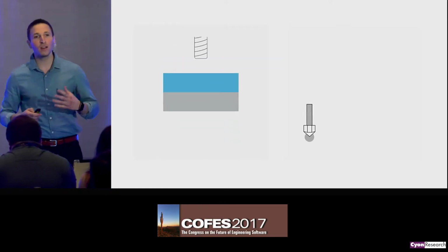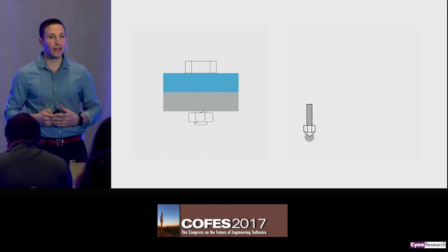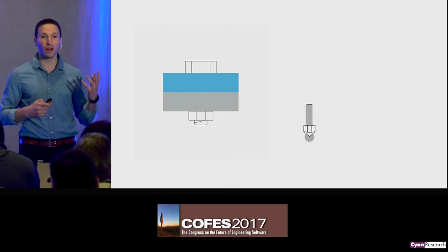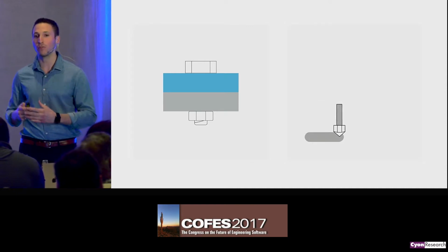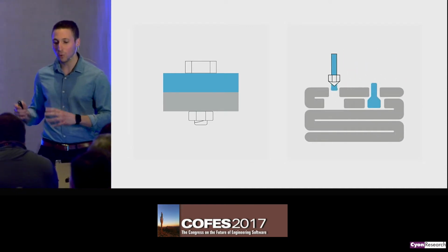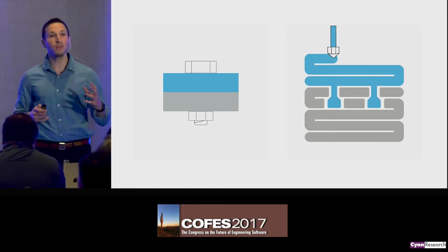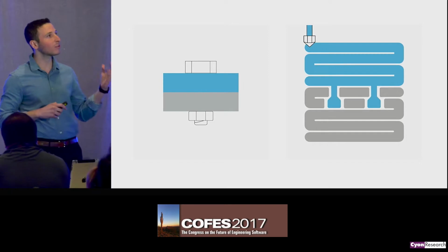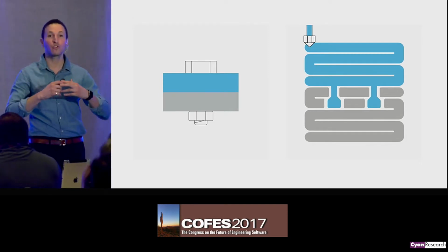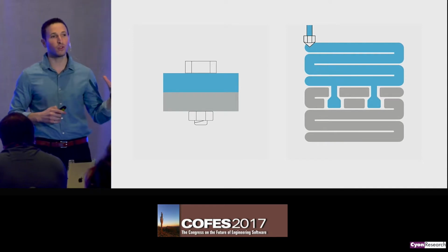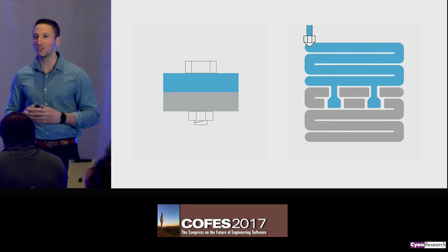So to solve this, we created a technology called Mosaic Rivet. And what we're doing is effectively accomplishing the same goal as a bolt, but using a digitally defined rivet. A base material can be additively manufactured with receptacles in it that a second material is bulk deposited into to form a mechanical linkage, and then the second material is printed on there. So those two materials are interwoven together. Again, we're accomplishing the same function of a bolt, but this is a completely digital implementation.